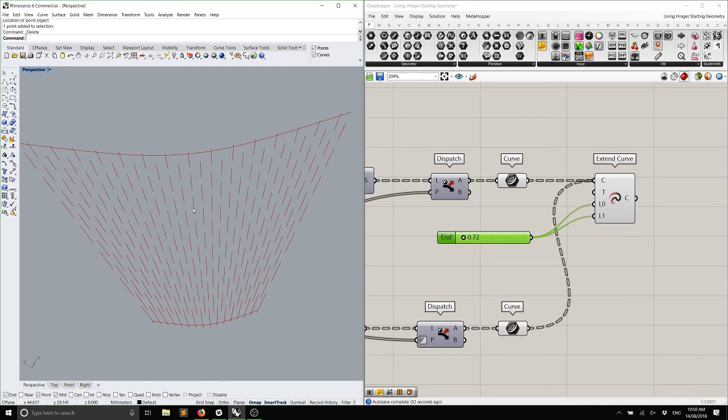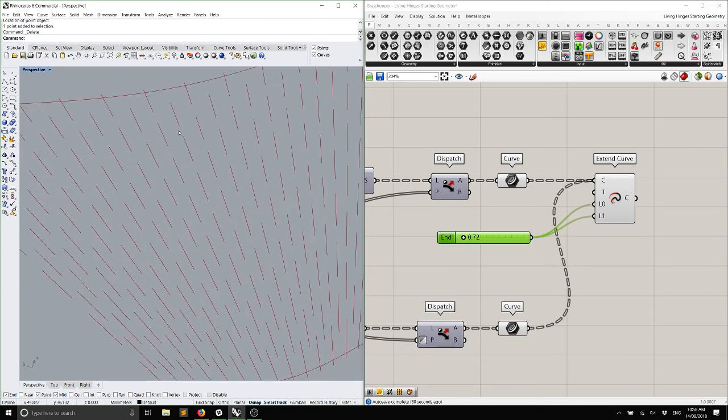If you make the spacing between these too wide, then your plywood might snap. If you make it too thin, then your plywood might snap, okay? Fortunately, the length of each of these elements doesn't matter so much, but the more connections you have from one section to another will generally make the whole thing stronger, more robust, but still curvy, okay?